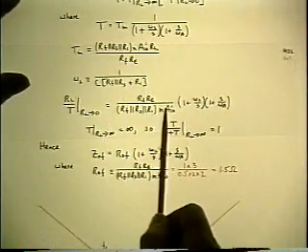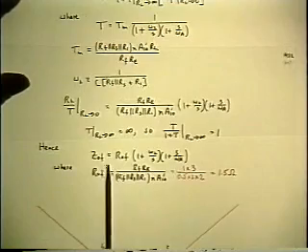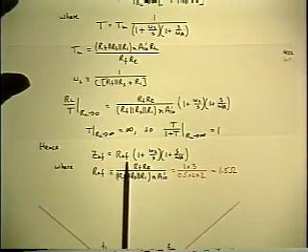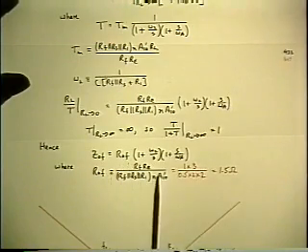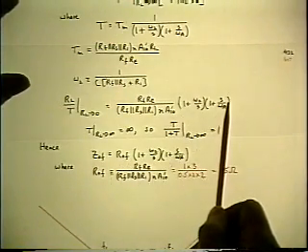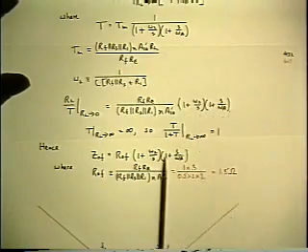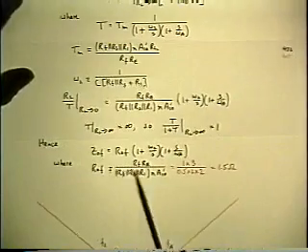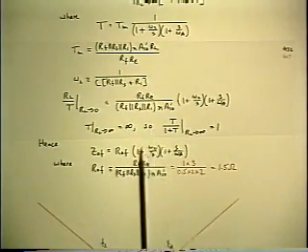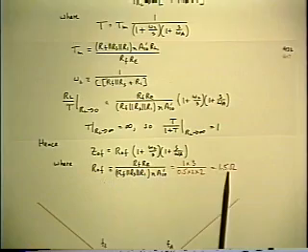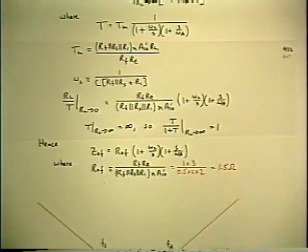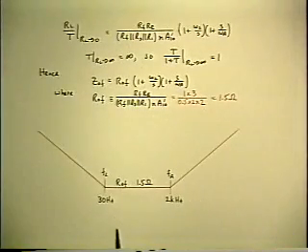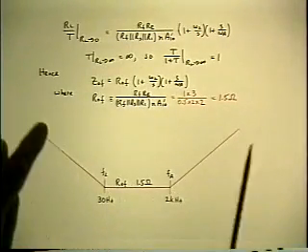So the coefficient in front has dimensions of resistance, so we call it the mid-band value of the output resistance with feedback, ROF, and there it is, and it has 2 corner frequencies, an inverted 0 and a normal 0, which are the same frequencies that were originally in the T. Numerically, the ROF is 1.5 ohms. And then the zeros outside that range cause the closed loop output impedance to rise.